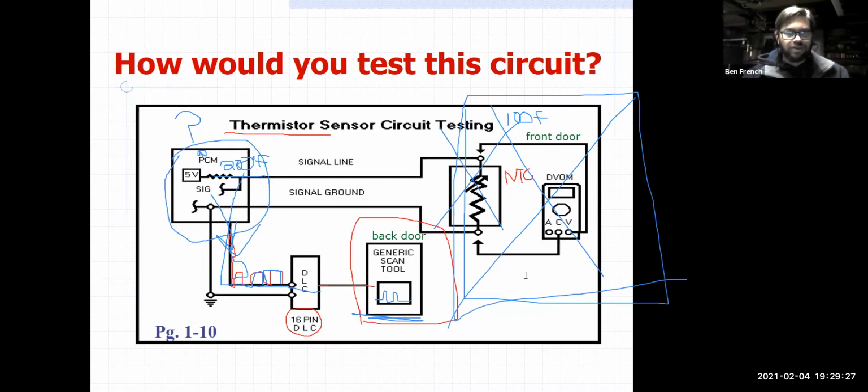But here's one of the nice things about OBD2 generic. If you have your tool and you are pulling the generic data, that's the data that the government, the EPA says, okay, we want these things in this generic data mode, it's not supposed to lie to you, okay?